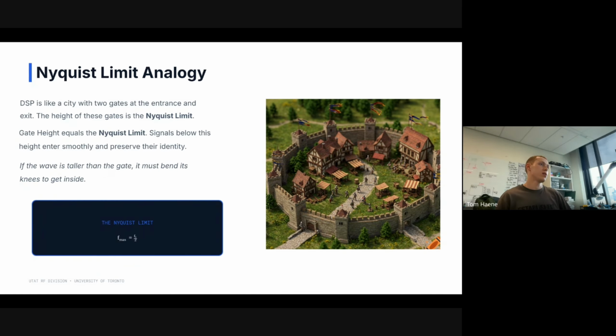20 kilohertz. Okay. Yeah, I should be more precise. So I know that all of audio is 20 to 20K hertz. If I want to capture all possible things someone could say, I should make sure my gate is tall enough. Because if it's 10K, my Nyquist limit, I'm going to lose high-pitched noises, and it's just going to be a bunch of low-pitched stuff, and my song is going to be messed up. Is that kind of making sense so far?